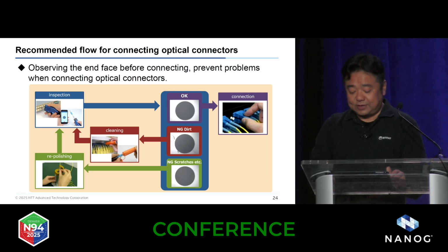If it is scratched or has an old polishing grade, as explained earlier, you can restore it by polishing it. Polishing may seem difficult, but there are some handy polishing machines available nowadays. Polishing is now easily possible on site, so don't give up if you have an optical connector with an old polishing grade which is hard to replace.